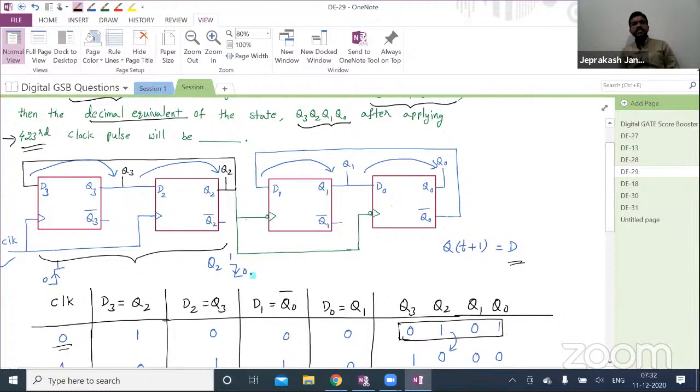Yes, very good, Rajshekhar. It is a ring counter. See, in the ring counter, you will use D flip-flops, and for all the D flip-flops you will have the same common clock signal. The output of one stage is given as input to the next stage. The last stage's normal output is given as the serial input for the starting stage, right? So it is a 2-bit ring counter.